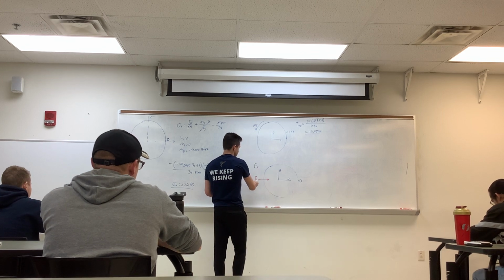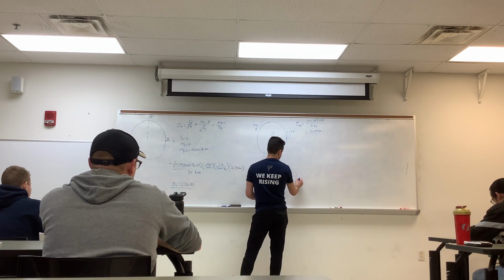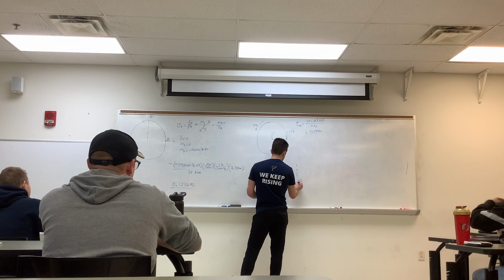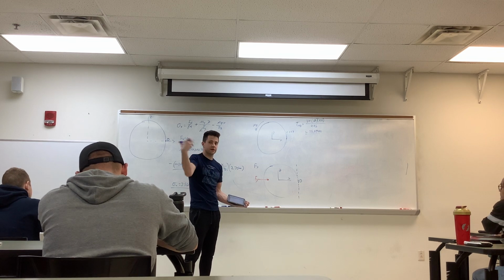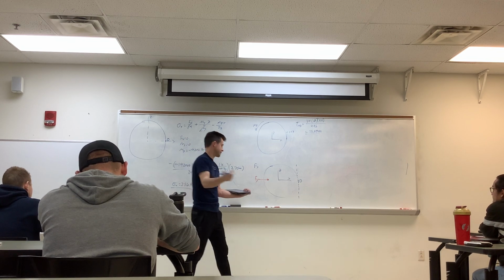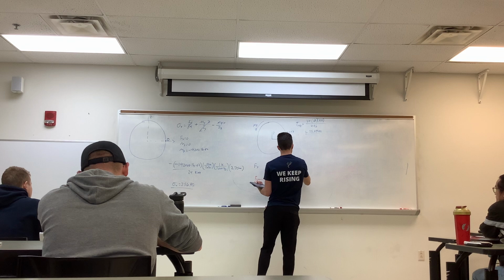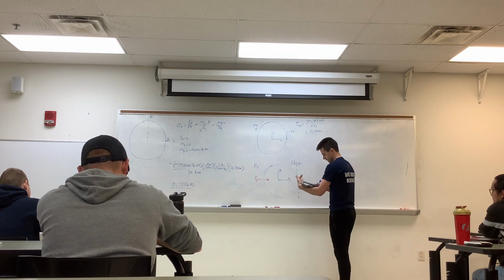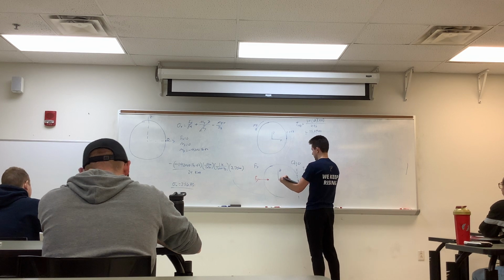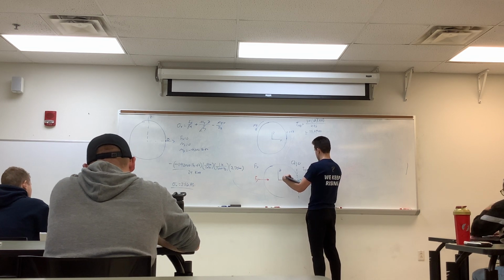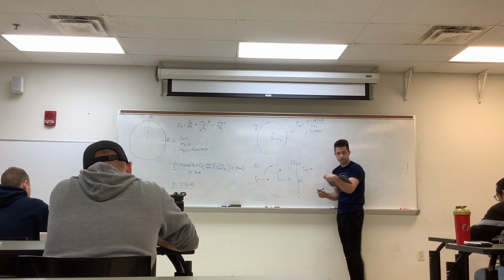But at point D, when we're calculating our shear flow, you take a cut across that area. And this is that case where you either cut off the entire thing or nothing at all, giving us no shear flow, giving us this tau sub x, y is equal to 0.